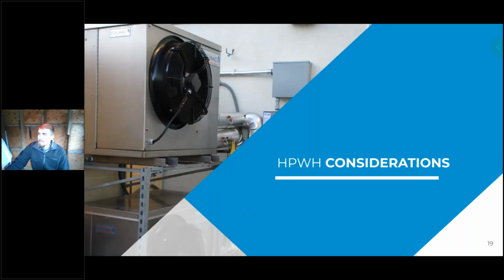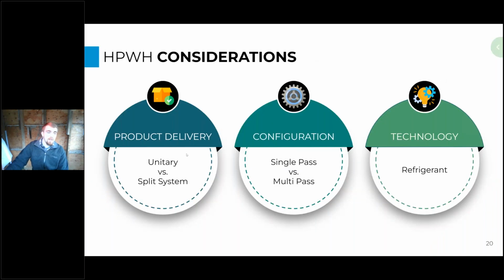Yeah, so now we'll talk about the considerations we'll need to make to design around these heat pump water heaters. So that will include how these heat pumps are packaged, whether it's a unitary or a split system. It'll talk about the plumbing configuration we'll use with these, whether it's single pass or multi-pass, and then we'll talk about the importance of the refrigerant that's operating in your heat pump.